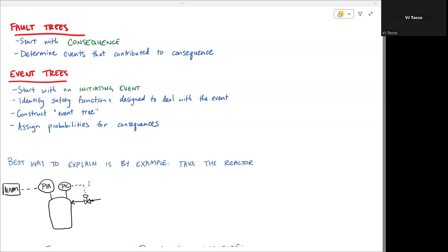The second system is a PIC, Pressure Indicator Controller. And here what we're doing is attaching this to a solenoid valve, and the solenoid valve would open. Presumably there's cooling water in this pipeline that would do the same thing, that would quench the reaction very rapidly in the event of a high pressure system.